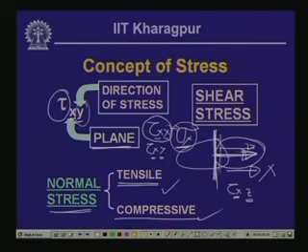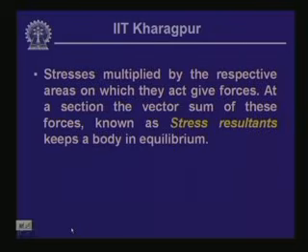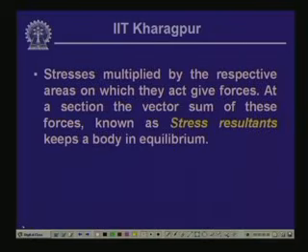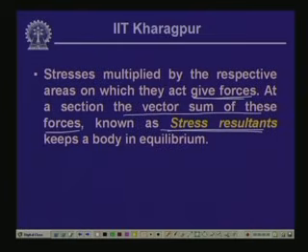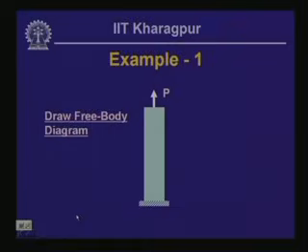Also, the stresses which act in the plane of the cut we call shear stress. Stresses multiplied by the respective areas on which they act give us the forces, and at sections the vector sum of these forces is known as the stress resultants. Basically, in problems of strength of materials we are interested in evaluating these stress resultants, and from them we compute the values of the stresses in a body subjected to different kinds of loads.